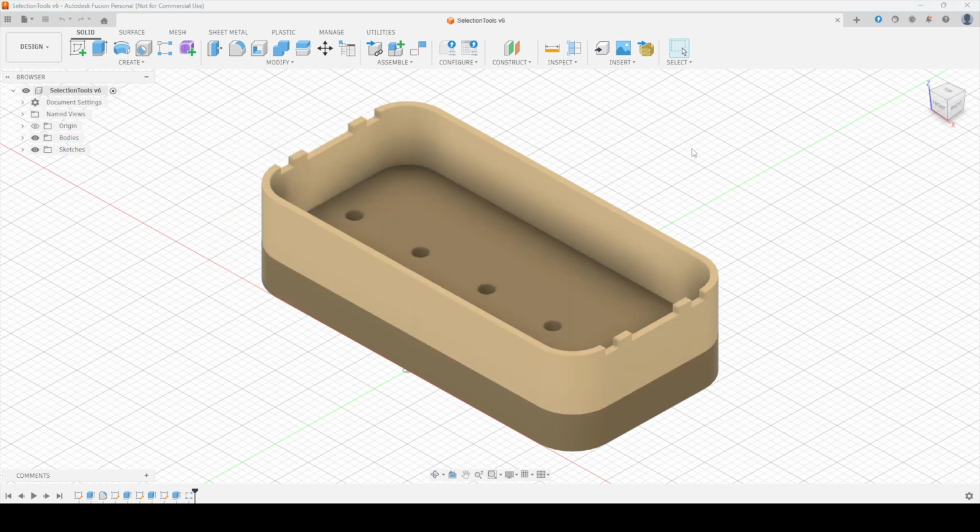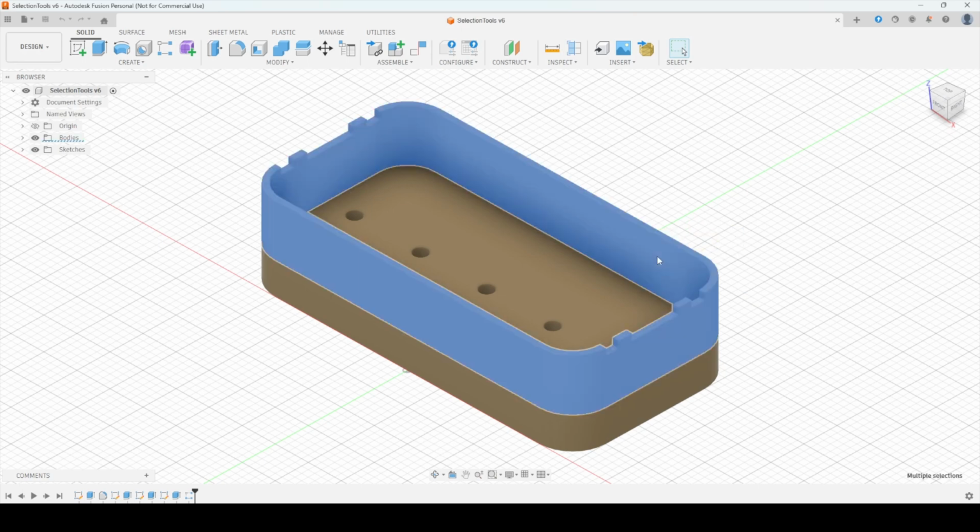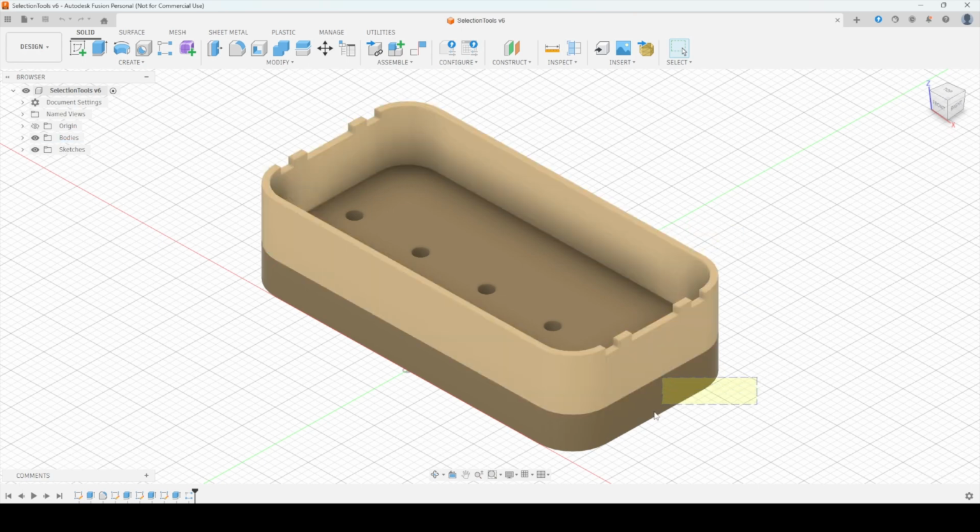There is also another type of window selection, called crossing window. To create a crossing window, click on the right side and drag to the left. You'll notice the window border becomes dashed. With crossing selection the rule is different. Everything inside the window and everything that the window touches gets selected. Because of that, crossing selection often selects more objects than you originally planned, which can be useful but also something to watch out for.